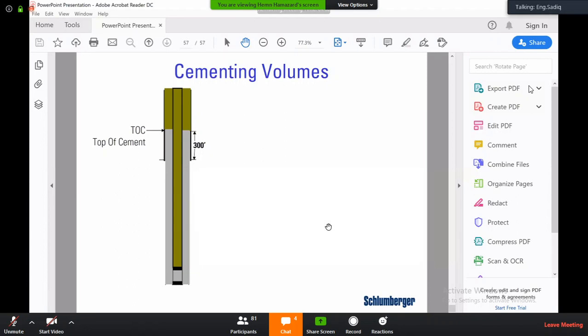Go ahead. So can we drill a well using just one type of casing, or should it be a set of casing? Okay. Now, there is no way to drill any well with one casing size in one casing section. Any well is in a tapered shape. You have a bigger hole and a bigger casing, and then a smaller hole and smaller casing, smaller hole and smaller casing. There is no well in the world with one casing. I've never heard of that.